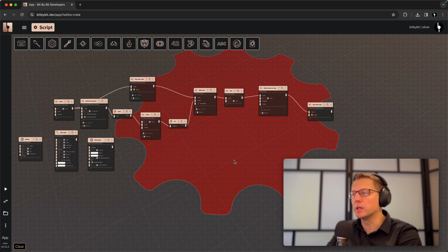I will also use the divide wire by params to points command. I'll want 5 division points, and I'll hide this face for now so that we better see what we do. And I will create again circle faces on top of these points.